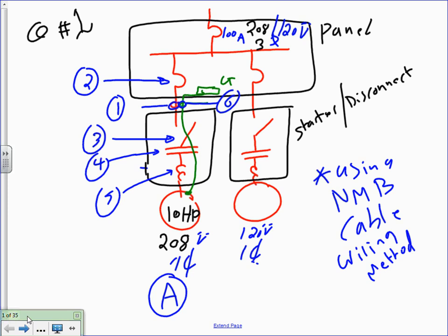Does it matter? Everybody knows it's a 208 system. So it's 208 single phase, 2 hots. And I need to find, starting with the conductor, the branch circuit overcurrent device, the disconnect, the controller, as well as the overload. Can I have thumbs up, Chad?